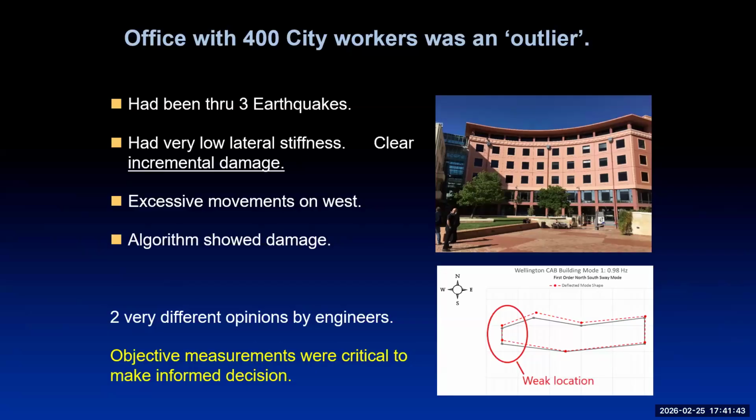So they asked us to tell them out of the 10, which was the bad one. Well, we said it's this one, it's damaged here, and you've got a failed member on the 3rd floor. And sure enough, they tore a wall off and they said, wow, those diagonals had failed. So it was a pretty powerful example. It created a condition where they could repair the building. They made other decisions, but in any event, it was quite an interesting project.